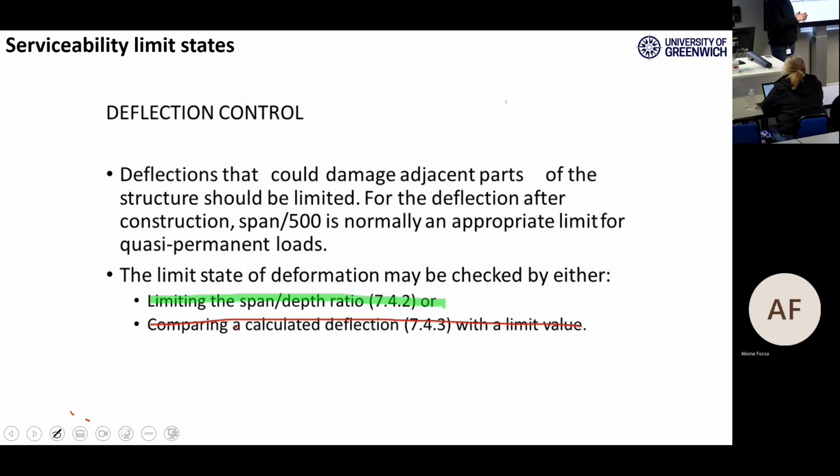You need to go to some more criteria. It's not just a simple table. It's just going to calculate your deflections based on some criteria in ETABS and bring them to compare with the limits, with the acceptable thresholds, to see if they are good or not, right? So it's a little work needed.